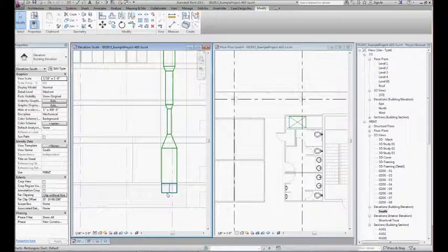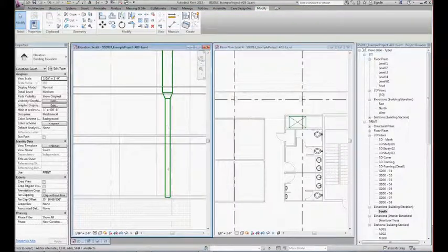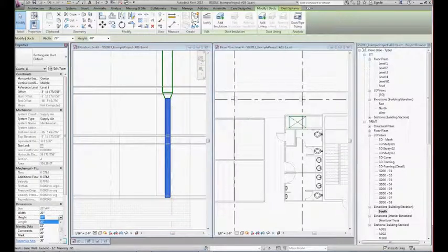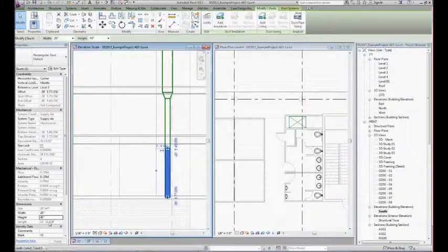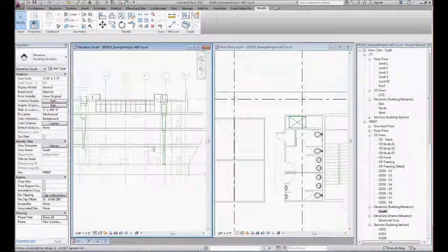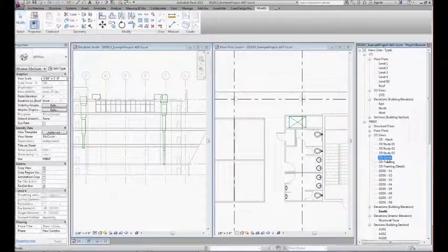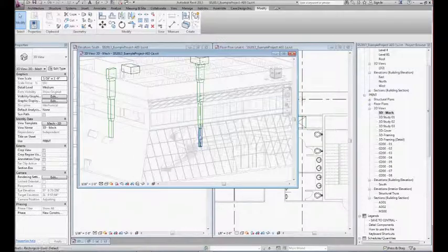well, you'll see something interesting happen right here. If I make this 20 as well, you'll see that it actually just joined it back up and made it into one long duct again. If I make that 2020, whoops, I have to split that. Maybe make that now into a 2020. You'll see the transition, but it's really transitioning in the other direction, so you can't see it from here. If I open up my 3D view, you start to see what we're looking at here.